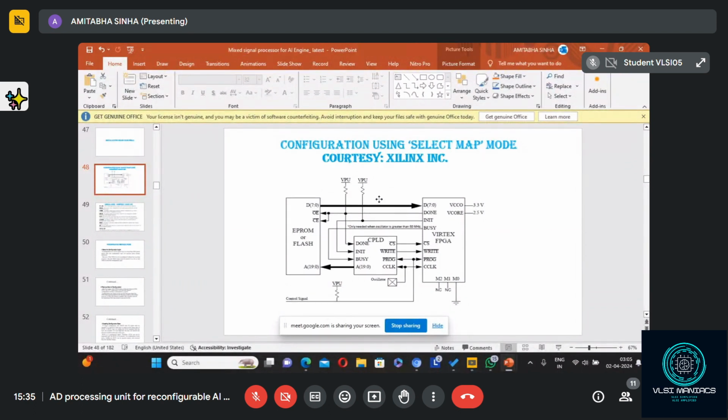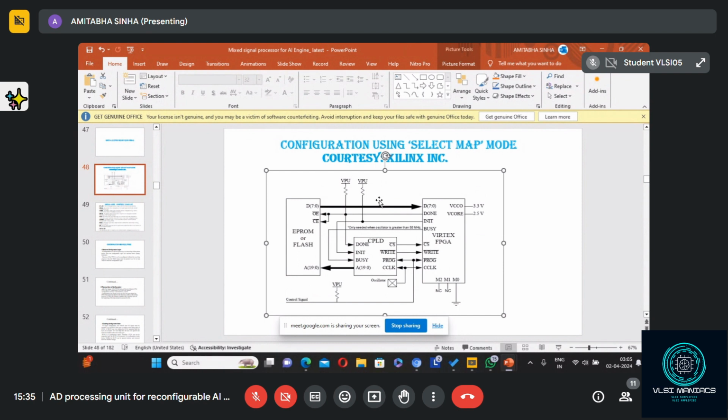That signal indicates that programming is done. So the CPU understands that programming is done. Programming is done means the FPGA will now behave like the hardware for that particular function. So then the CPU can send a command to the CPLD to execute it. Then it will make the program bar signal high.